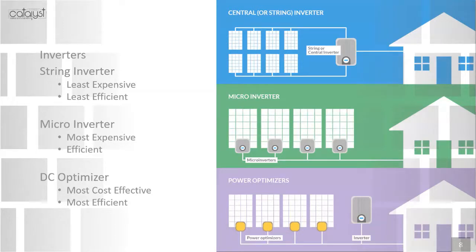So I'm not too concerned on those deployments. It's still the most cost-effective, efficient way, assuming everything's facing the same direction and everything has the same tilt angle. String inverters make a lot of sense. But on the smaller scale side, when I get into residential rooftop deployments where I may have east-west, I may have dormers, I've got modules on the same string that I want to face in different directions, that's where a regular string inverter starts to fail.